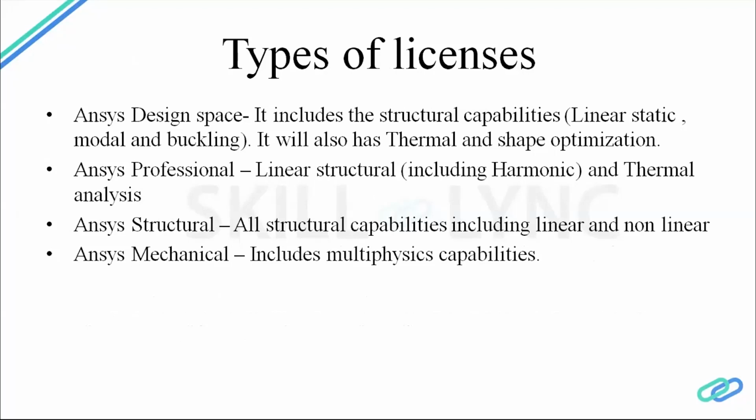So basically there are many licenses available in ANSYS Workbench. ANSYS DesignSpace is a basic license available, which includes linear static, modal, buckling, and also some thermal analysis. And higher ones like ANSYS Professional, ANSYS Structural, ANSYS Mechanical include the previous things, but extra things like harmonic and thermal analysis.